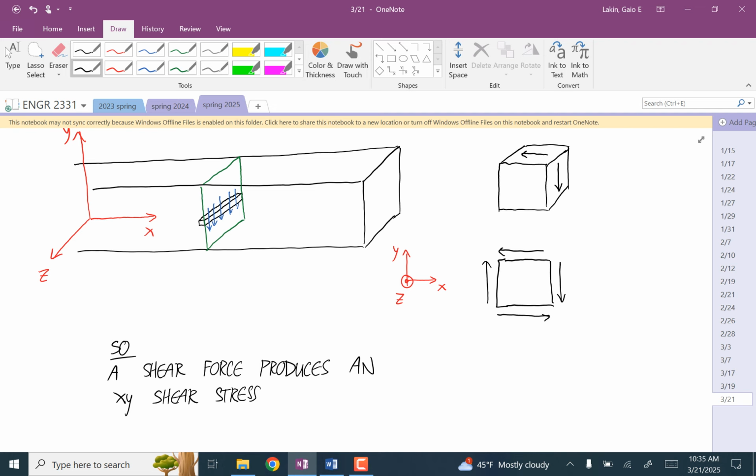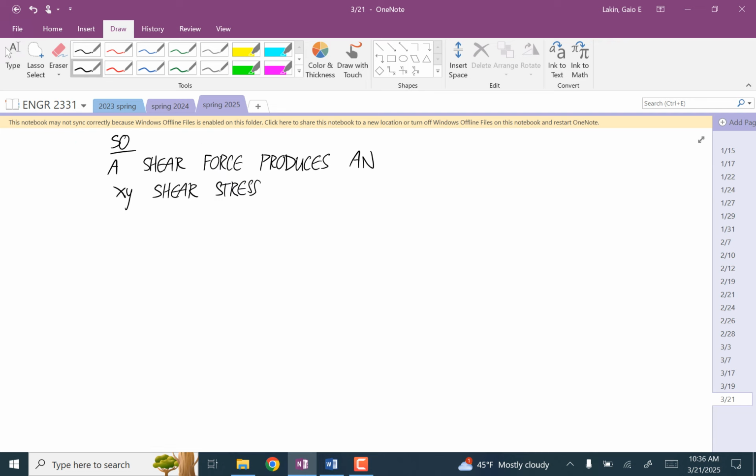And if a positive shear force is down and leads to those stresses, that means we're going to have a negative relationship between the shear force and the shear stress, and that's where the negative comes from in this formula when we get to it. Before I give the formula, let me give the beam requirements.